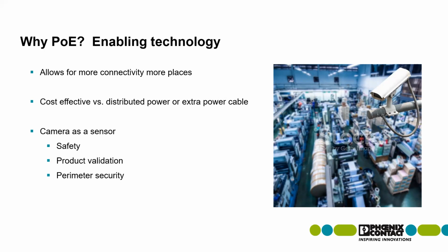It's getting not just the data out there, but if you can do it in a more cost-effective manner, now when you're looking at a new application, you can get that sensor or those edge devices connectivity by justifying it, saying, hey, we'd have to run a power connection out here anyway. Why don't we save that money? Just run an Ethernet connection out here. That'll provide not just the power for that device, but it will allow us to communicate with it, pull data from it, and let it be part of that IIoT infrastructure.